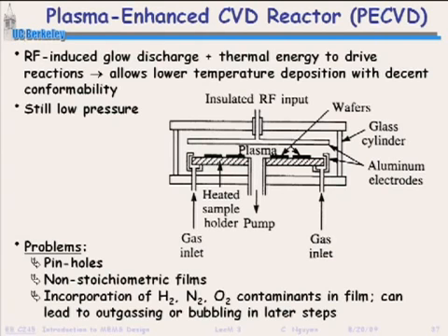Okay, that goes to etchers. I'll give you a piece of advice here. Never trust an etcher, period, if you're doing processing in a nano lab at any university. Even if the person before you was conscientious enough to put down his or her etch rate, do not trust that number. Because there's all sorts of different things that decide on etch rates. Now, always determine your etch rate yourself with a dummy. Okay, that's just an aside right there.